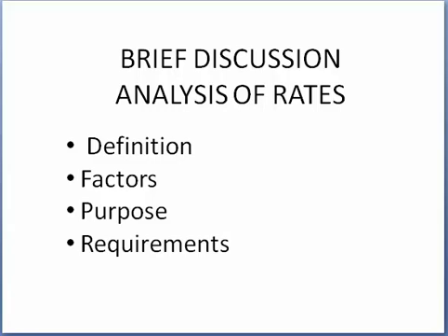Third, output of machinery and labor as per CPWD analysis of rates, which is obtained by the practical experience of the engineers for working out the cost of the item. Then factors for dry volume as per CPWD analysis of rates, and then the current rates as per CPWD.